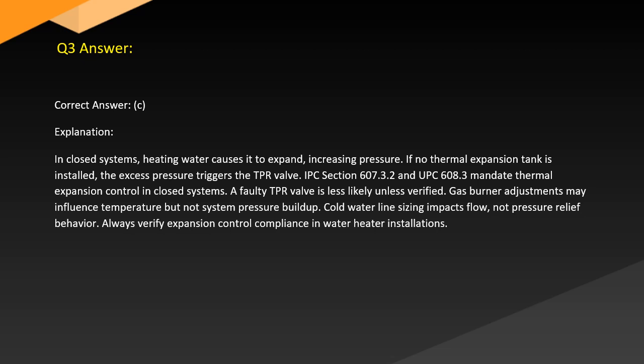A faulty TPR valve is less likely and less verified. Gas burner adjustments may influence temperature but not system pressure buildup. Cold water line sizing impacts flow, not pressure relief behavior. Always verify expansion control compliance in water heater installations.